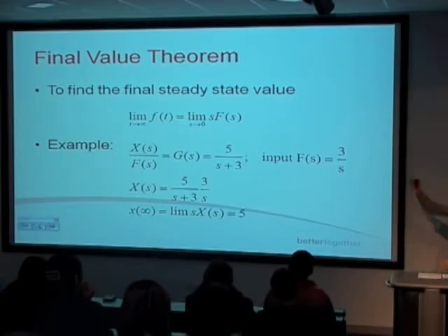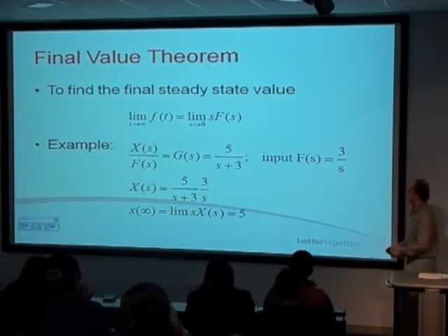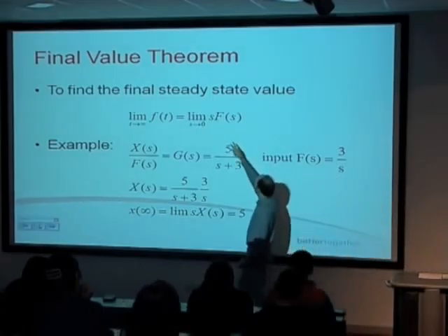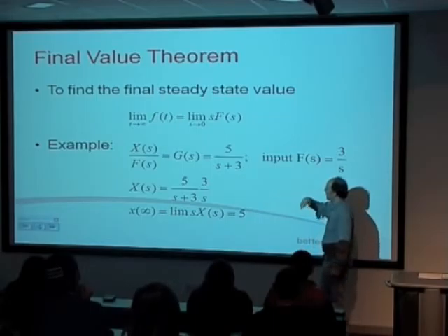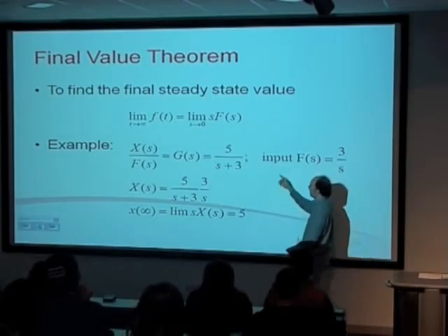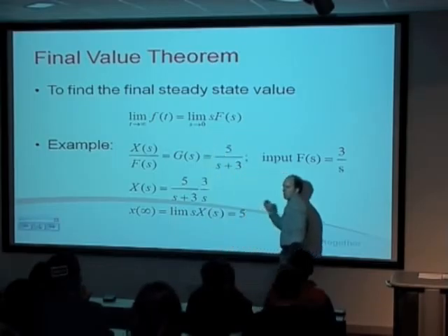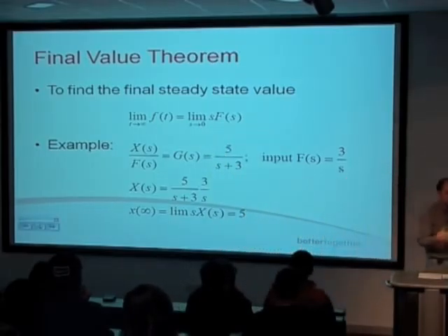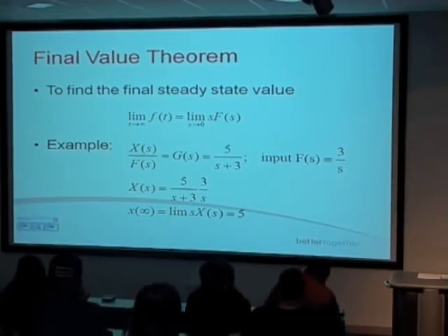So that is the final value theorem, this line here. That's what you need to remember. Like I said, if you want to call this C of t and this big C of s, then you can do so. In this example, I've called it x of s. Whatever, just make sure you know that this is the final value theorem. And don't forget that s term. On the tutorial sheet, there's a few examples where you'll be applying this. It's quite simple and quite straightforward to do.